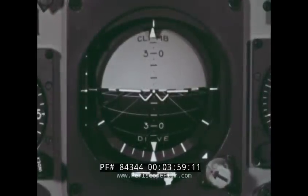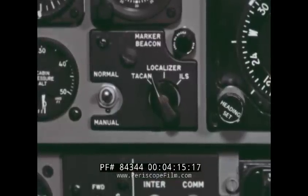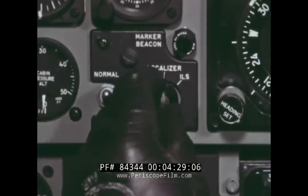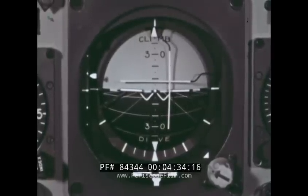The turn and slip indicator on the bottom of the ADI is a remotely controlled instrument. Its use is conventional. The slip indicator is the standard ball type. The bank steering bar has two separate functions. The TACAN manual mode provides steering commands and enables the pilot to maintain desired headings. The ILS normal mode provides steering commands which will allow us to intercept and maintain an ILS localizer beam.